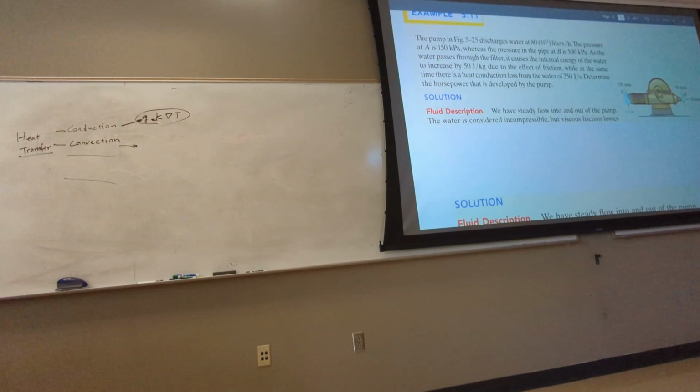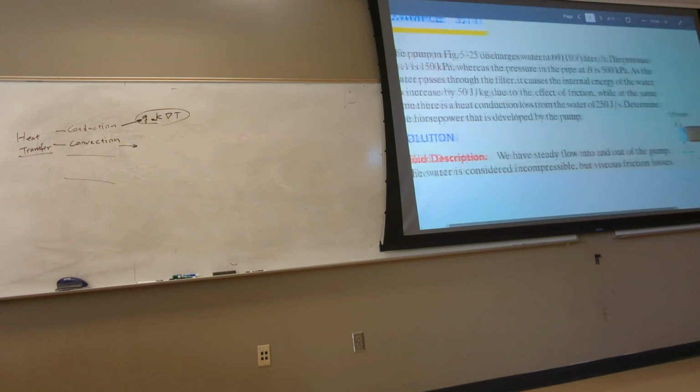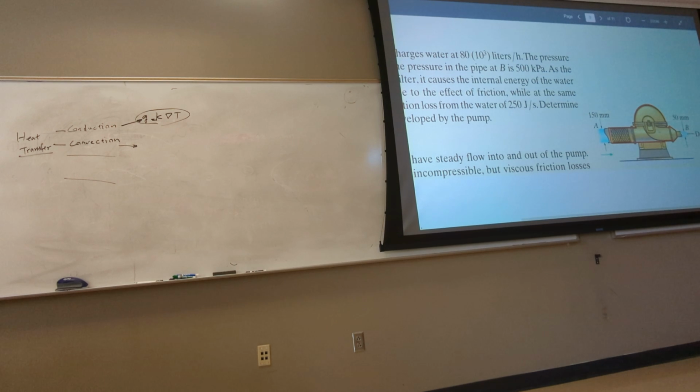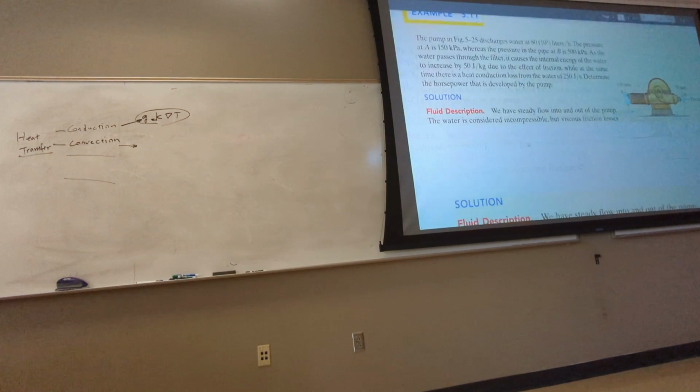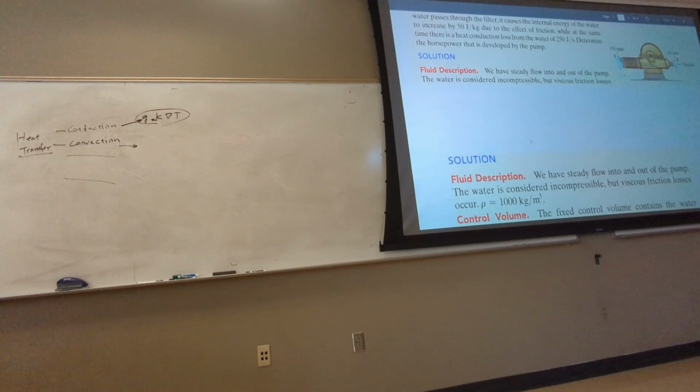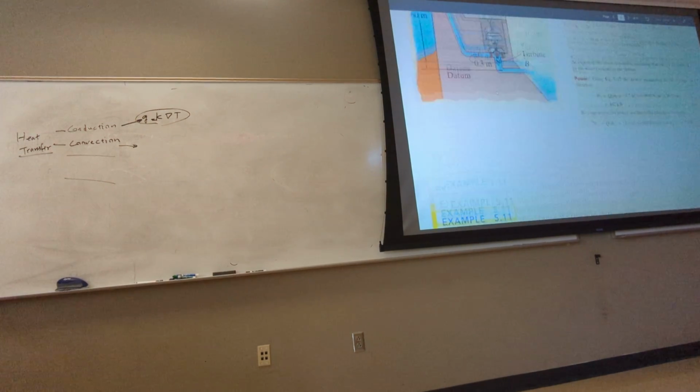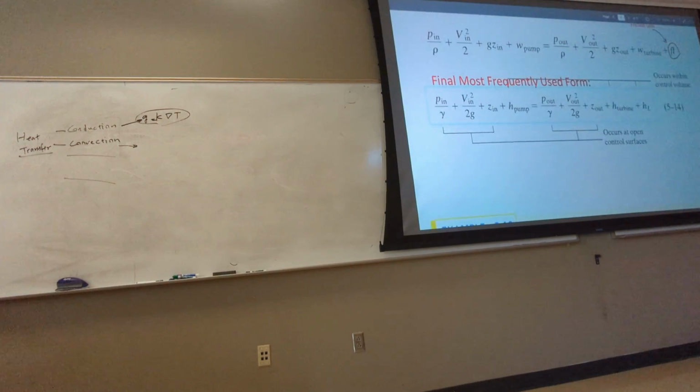So here, again, the control volume, you see that red line around the pump, that's the control volume. It goes all the way from inlet to outlet. So one thing about the energy equation, even though we're not going to do the triple integral distributed things, we have just a simple equation as you saw here. Even though we have this simple relation, you also have a control volume, because we derive the equation using a control volume. So you can't just memorize that, well, this is just energy.